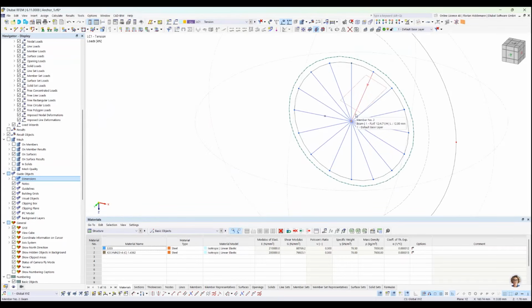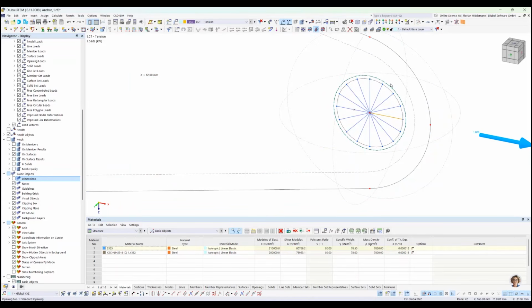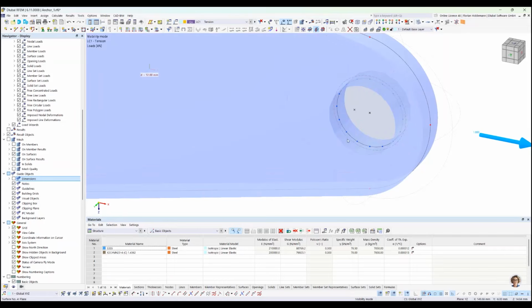As you might see here, we have some nonlinear members. And if I activate the transparent model, you can see that these try to simulate some weak beam section here. The model dimensions for these beam elements are chosen in a way that the surface area of the connecting part for the beam end is the same as the area for the cylindrical surface inside of this model. So if we just make them invisible, show the transparent model,